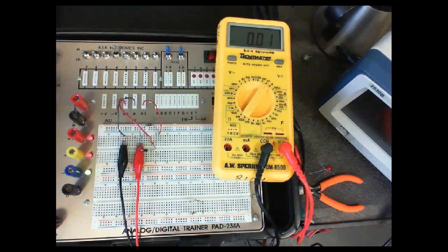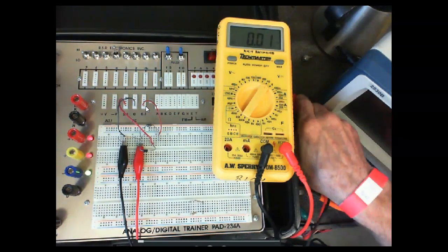Because of what your diode drops, that's 7/10. Well, no, we calculated a while ago with the 7/10. I just didn't multiply it by 2. That would still have come up and gave me about over 5 volts. So you're right, that could be this, but odds are this is not exactly 12.6 volts. So if we measure the AC voltage on our transformer, it's probably going to actually be less than 12.6 volts.